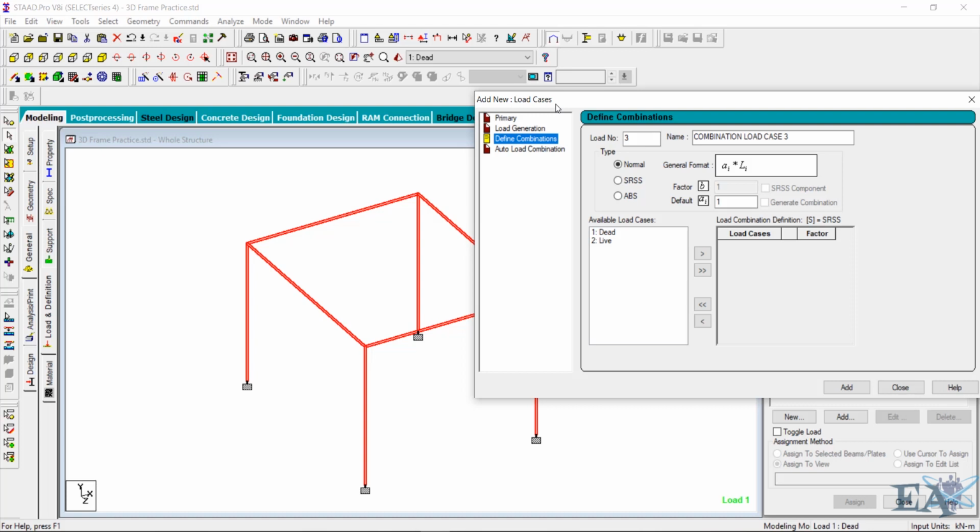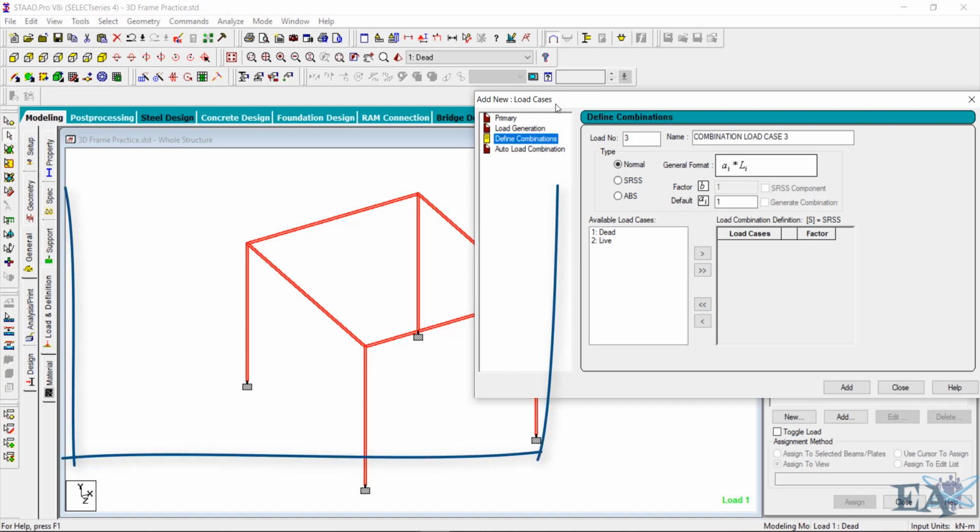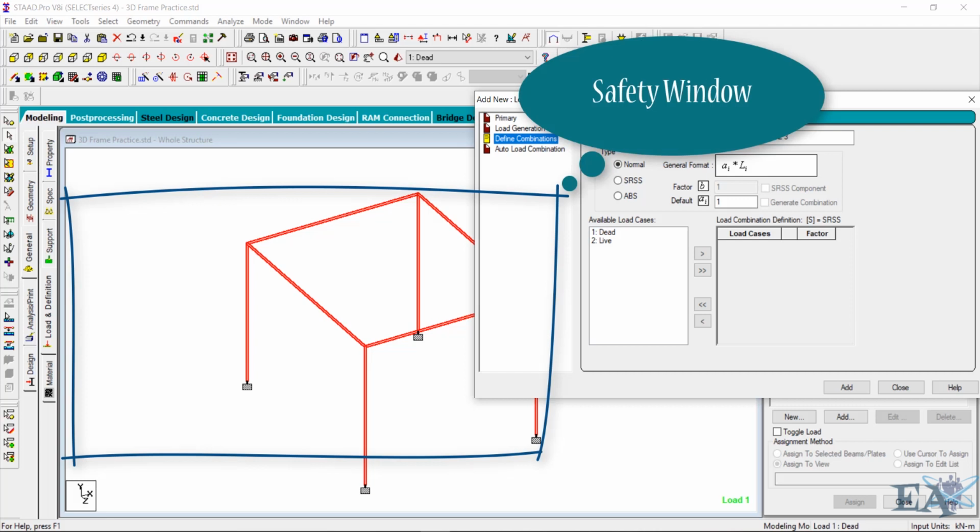Our strength is high, but we just assume during the calculation. So by increasing the load and by decreasing the strength, not actually decreasing, we get a greater window of safety. That is the limit state method.